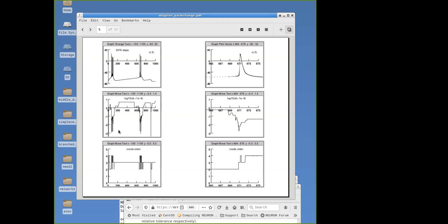If you force some parameter to change abruptly, if that's going to have any substantive effect on the simulation, if it's going to change, say, dvdt, for example, you may need to restart the simulation. It's a reinitialization of the adaptive integrator, in which case the integration order drops to 0